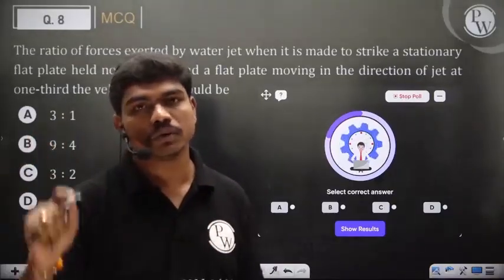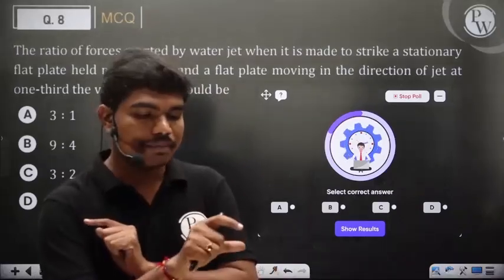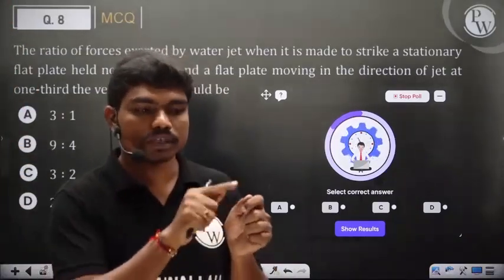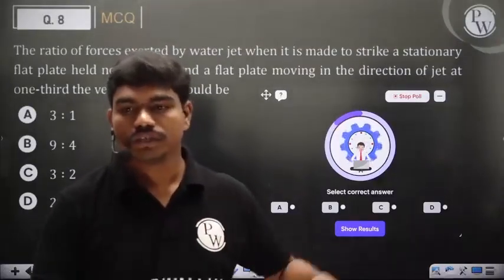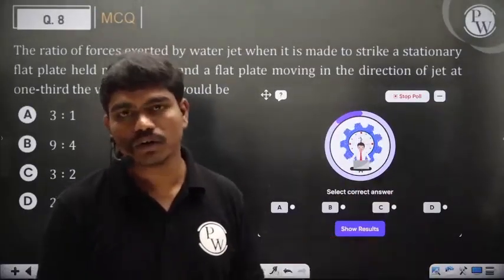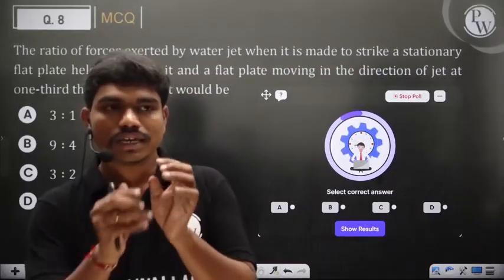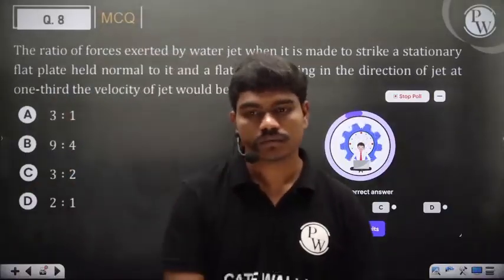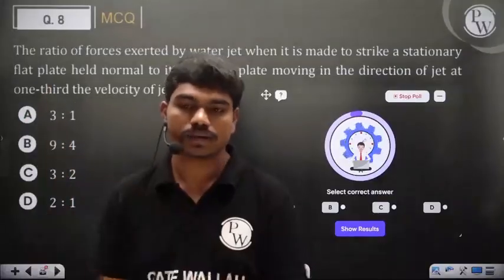For example, you decide to operate your turbine at a head of 500 meters, and in the lab you are testing. Then for the complete power requirement, you will check at what speed you should run the machine so that the scaling matches. When we go into more depth on pumps and turbines, we can observe this. But in general, that NST term should be made equal between the model and the prototype, because that connects the power and head scaling accordingly.